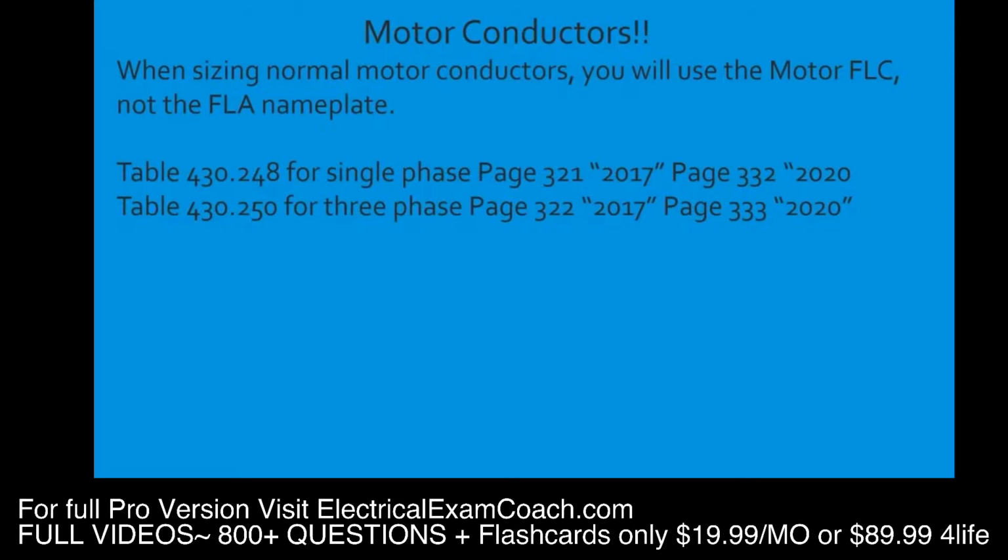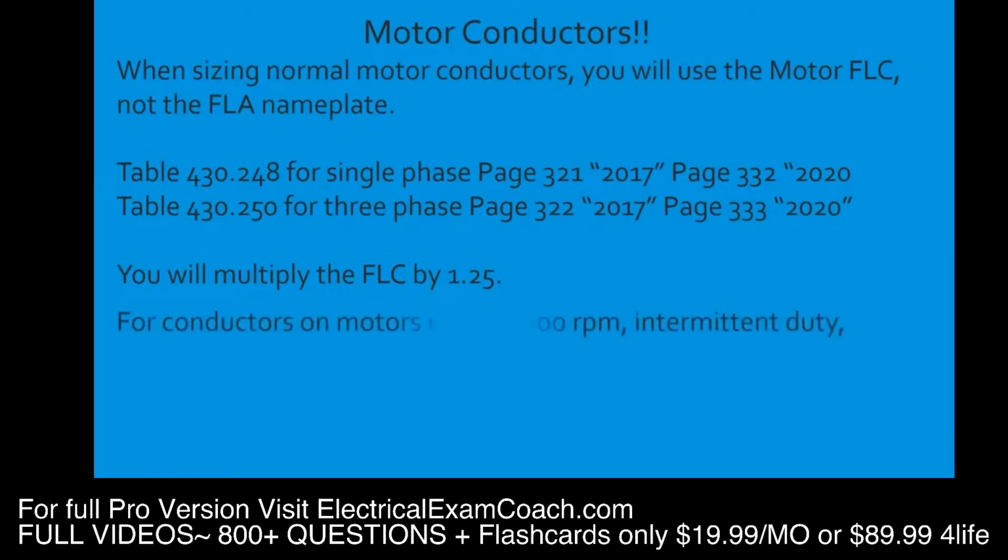Okay, now let's learn about some more ground rules for motors. You're going to multiply the FLC by 125%. They consider motors continuous duty. Remember how we learned about continuous load and continuous duty previously? Well, it's the same thing. They're assuming that all motors are continuous duty, except, remember this is the National Electrical Code, okay? Except when you're dealing with these certain circumstances, okay?